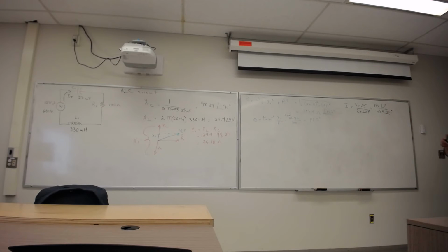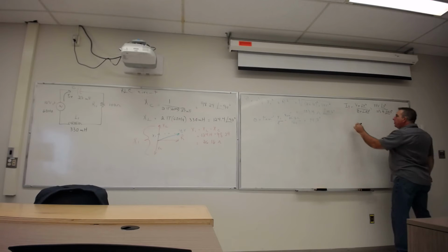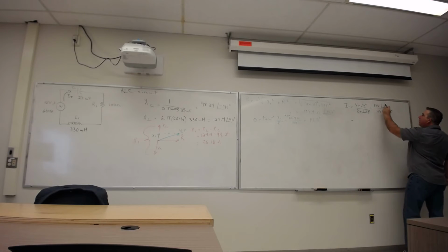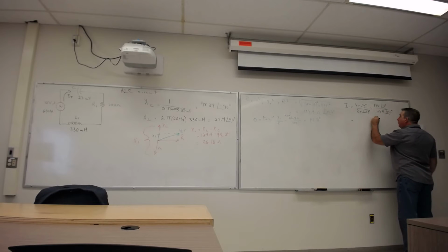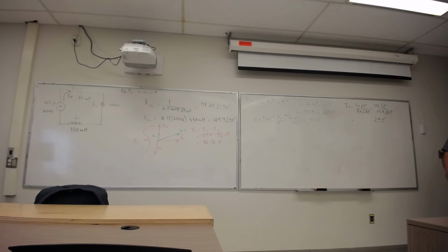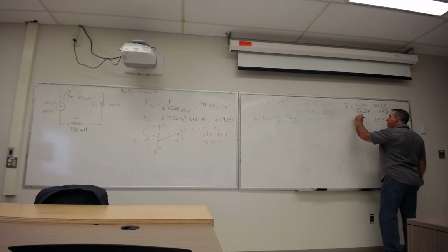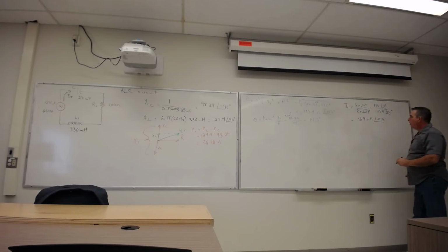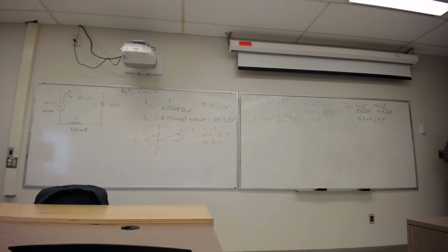It's probably going to be milliamps. That's what I'm thinking. So I know the angle. If I look at the angle, it's going to be 0 take away 14.7, so the angle for our current is lagging. It's at negative 14.7. If I do 10 volts and divide it by 103.4, what do I get? 96.7 milliamps. Holy crap, you guys did your homework. Good job, man.